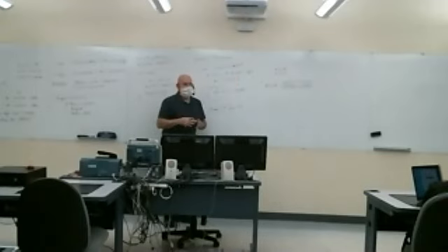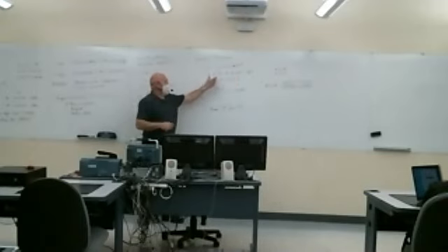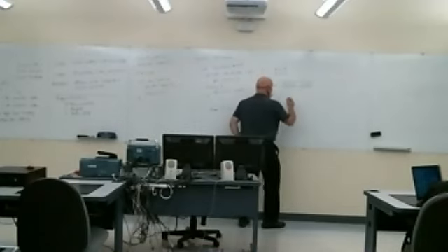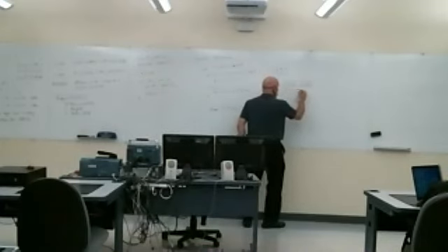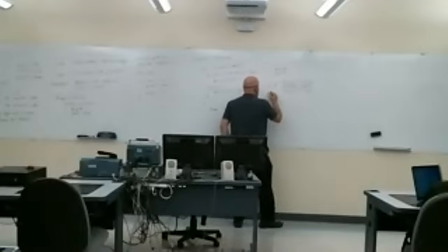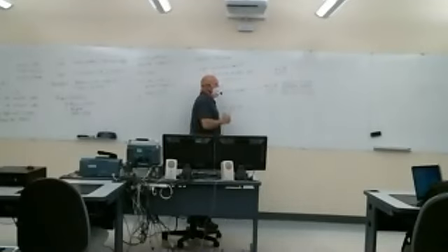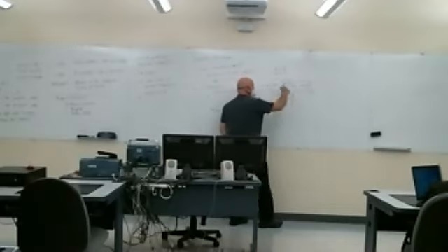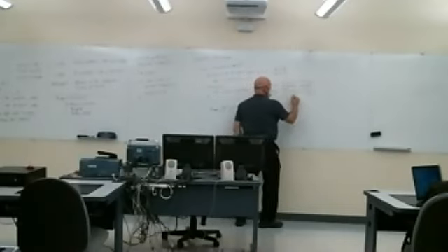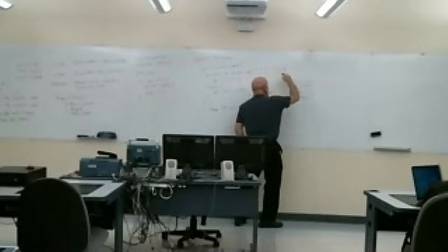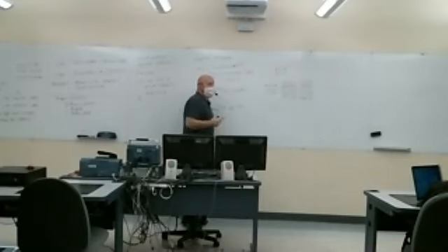This is a binary AND, so it's going to AND each bit in this 8-bit number with this 8-bit value. So 4 is going to be that. What does this ANDing operation do? Anything ANDed with 0 is 0, so we're really ignoring all of these bits except B2. B2 ANDed with 1 is B2.